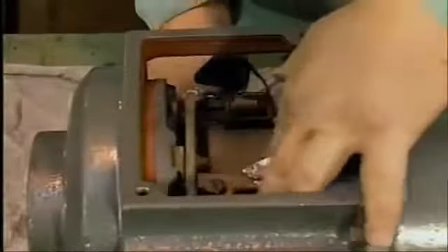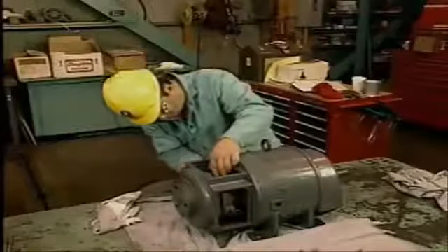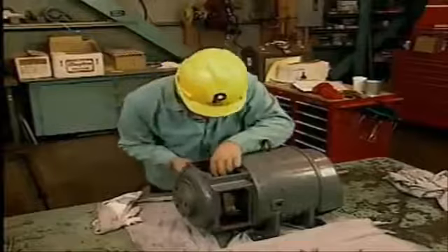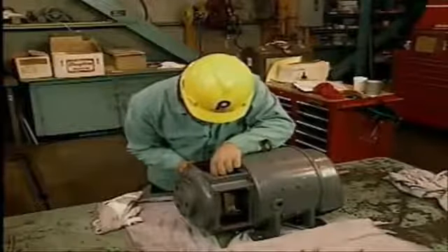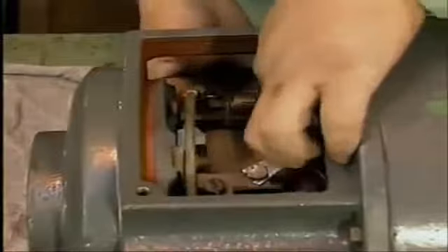The strip of flint paper is then placed on the commutator with the flint side out. The brush is placed in the brush holder, and the tensioning device is adjusted to hold the brush tightly against the flint paper. In this example, the motor's armature is then turned slowly back and forth a few times.